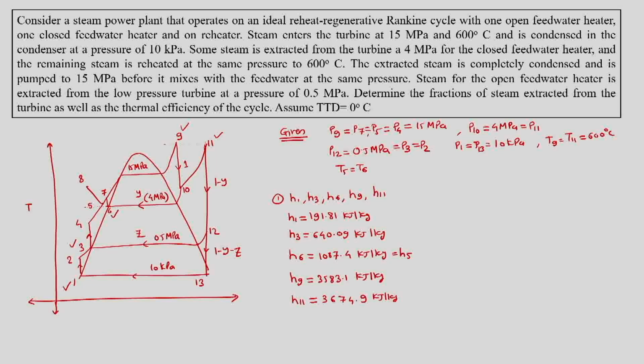This is one way to solve the example, where we can just make use of the steam table, and then we can monitor a few more things, where we will monitor the specific volume at state 1. This will be helpful for us to find delta HP1, which is the change in enthalpy in pump 1, and that is nu 1 into P2 minus P1, and we get it as 0.49 kilojoule per kg.